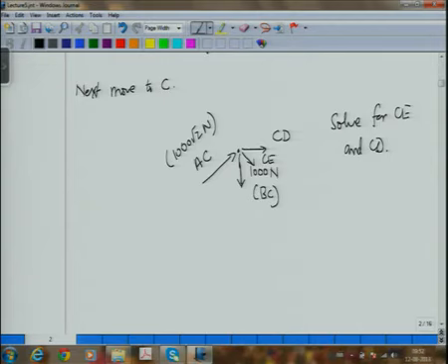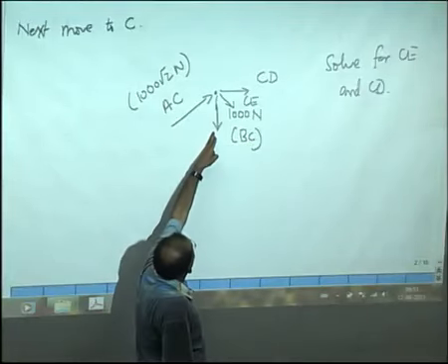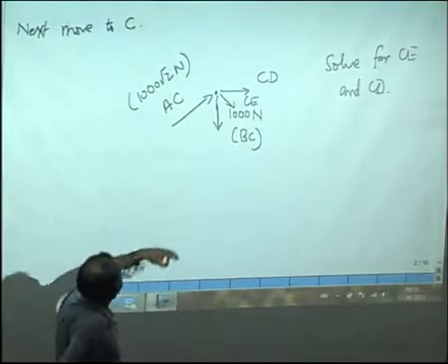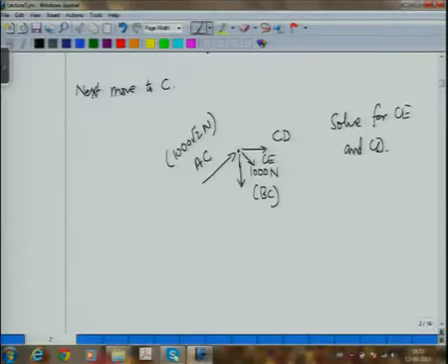You can work it out for yourself, get this thing, and actually what you will see is this 1000 root 2 newtons, if you see its vertical component, that will be 1000. So, that these two vertical components will cancel out, that means CE will be equal to 0. So, the way I have written this 1000 newtons, I will place it correctly here.